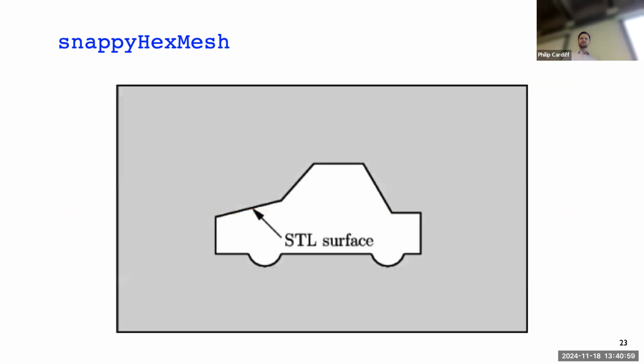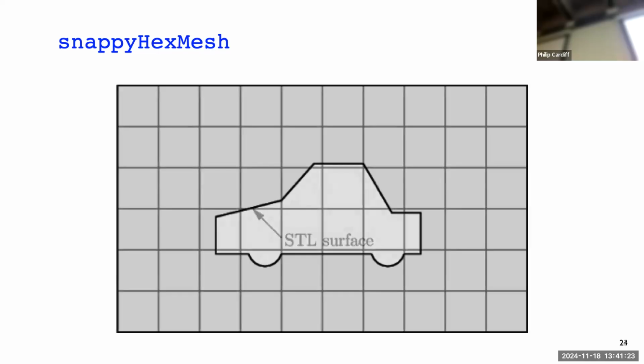So the way a Cartesian meshing approach works, and sometimes it's called an octree meshing approach as well, is you start with your domain, and then you have a CAD geometry. Often the CAD is in a faceted format, like an STL for 3D printing, which describes the surface in terms of little triangles. So not like an IGES or something like that. It's normally faceted. And what you do is you make a background grid over the CAD where you're interested in looking at the flow, so this is the flow around the car.